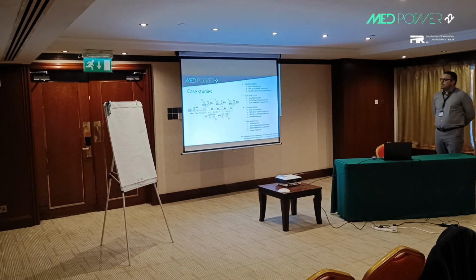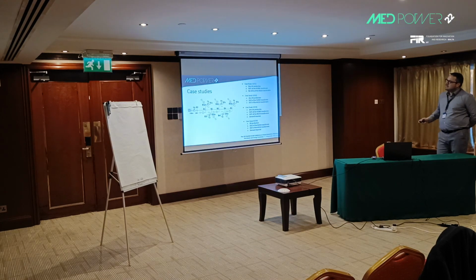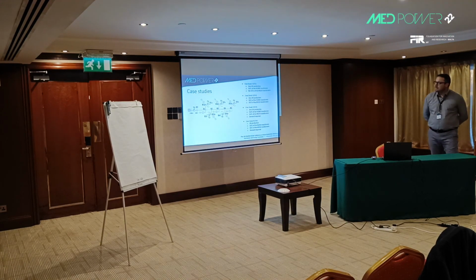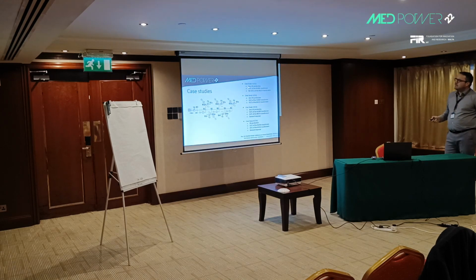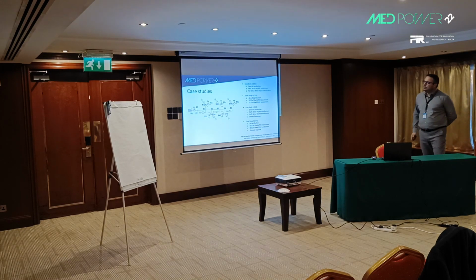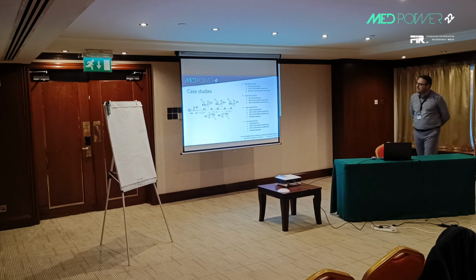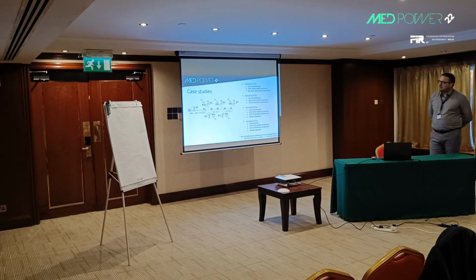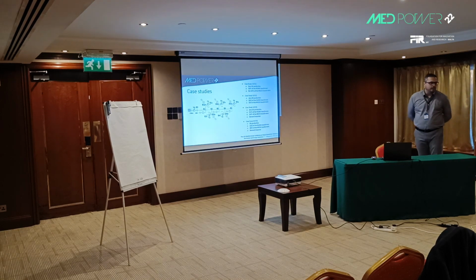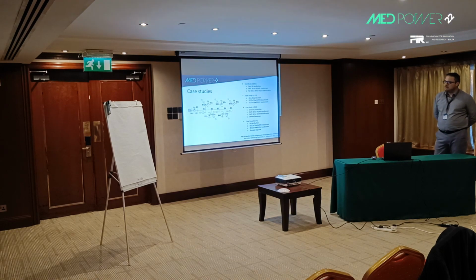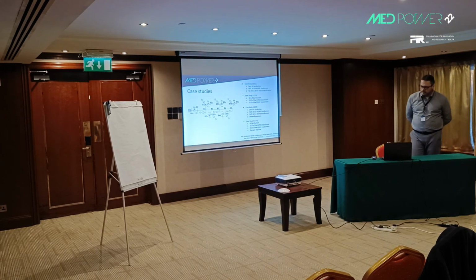We studied 4 different cases. The first 3 cases assume 0 DG production. In case study 1, only the main transformer regulates the voltage in the system. In case 2, the medium voltage, low voltage distribution transformers are also left to regulate the voltage. In case study 3, demand response is also applied. Finally, in case study 4, DG production is also assumed, and all the examined measures are in action.